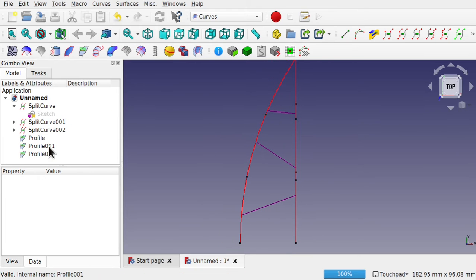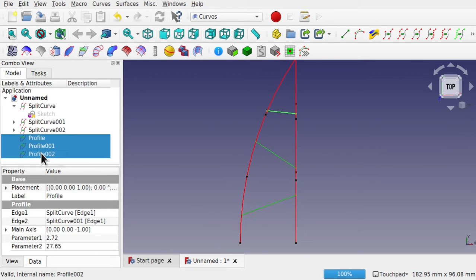What we can then do is shift click, so we can select them all, click the first one, shift click the last, come down to parameters, set that to 0. You can see those. If we set this to something like 100, and we can do that for our last parameter as well.